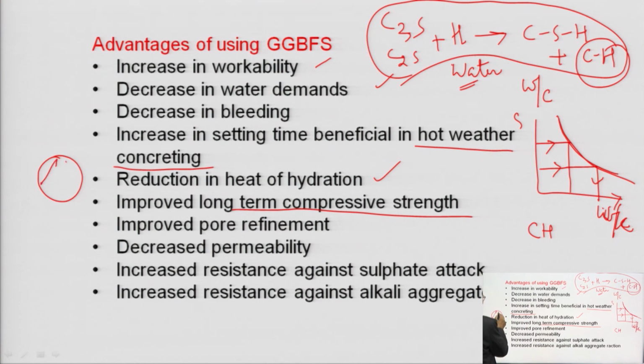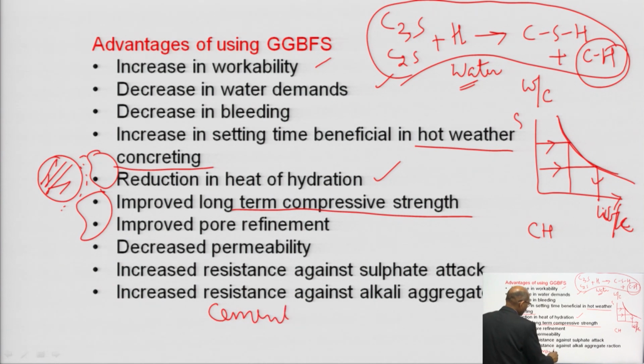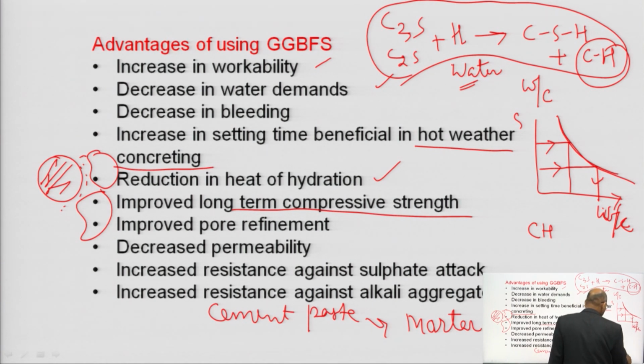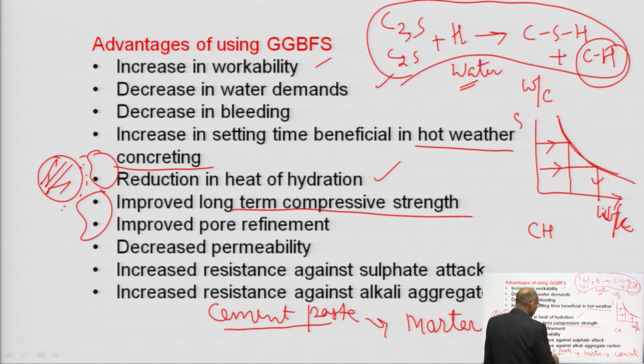If you consider GGBFS, the permeability of this type of concrete, if mortar is there, if you see the cement paste, okay, we have a cement paste, then from cement paste we can get the mortar and from there we can get the concrete. So, what will the cement paste consist of? The paste will be nothing but cement plus GGBFS plus water, and that is going to give you the refined pores. Okay.